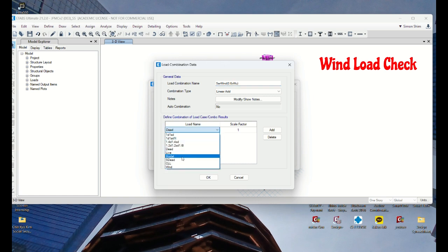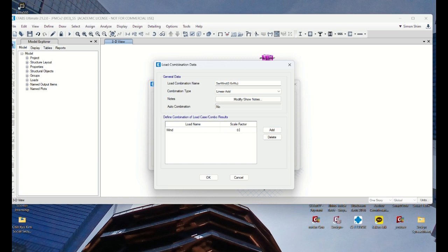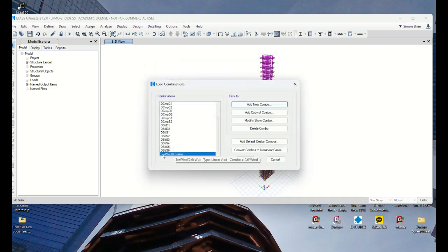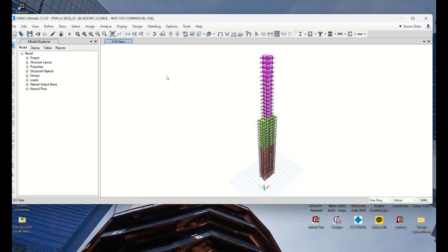So whatever wind loads based upon 115 miles per hour, the load factor 0.6, which is typically similar to 1 divided by 1.6, right? But code just rounds, so they're using 0.6 to scale down to service wind. So this is the service wind we're using for deflection check.